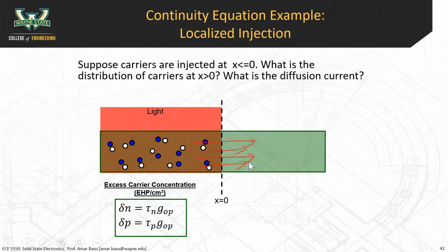All right, so recombination is happening on the left side. Is recombination happening on the right side? Yeah, close to the concentration gradient. Exactly. Great point. Why is there more recombination near the interface? Because you only have the light shining on the left side. Exactly. Light shining on the left side, so you're injecting carriers onto the right side.